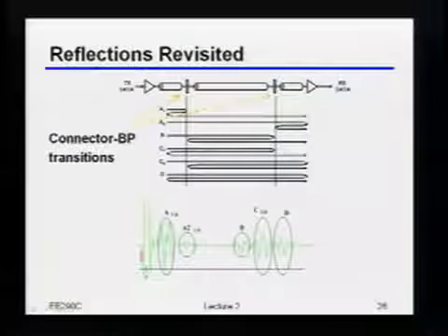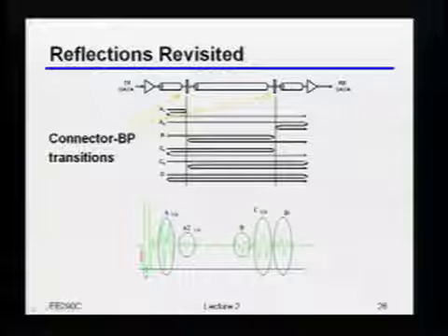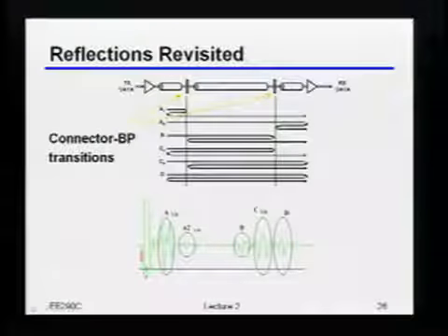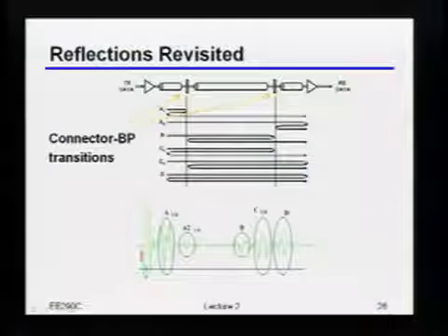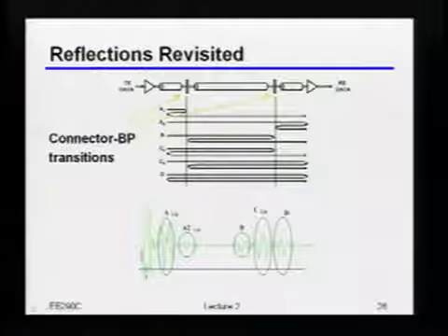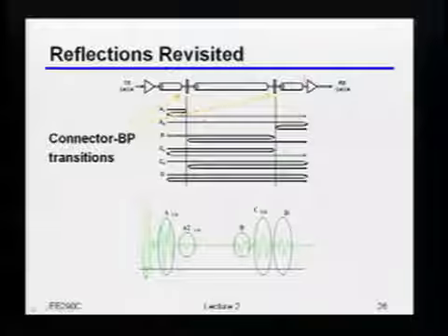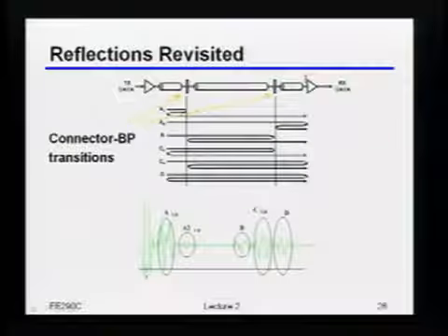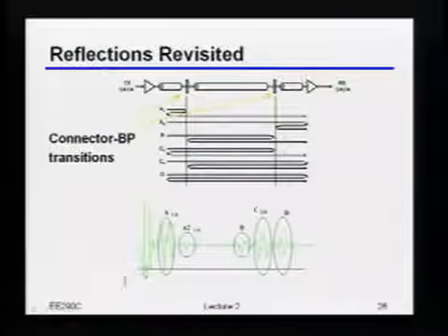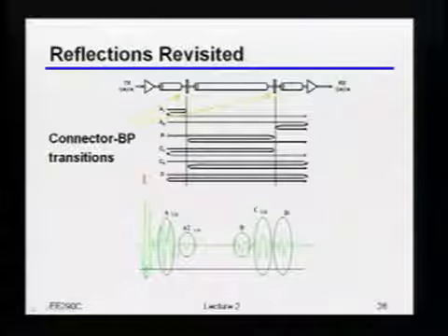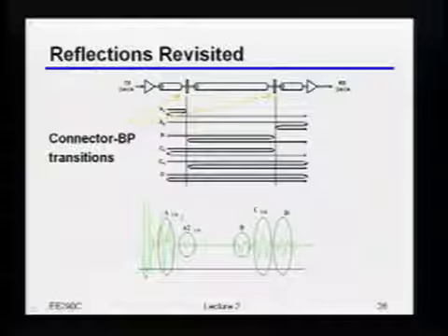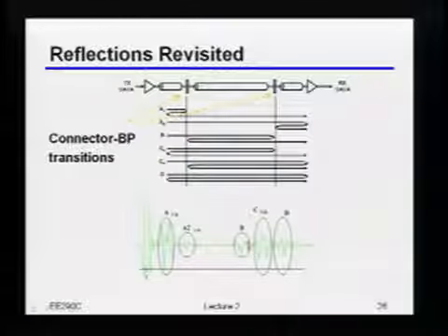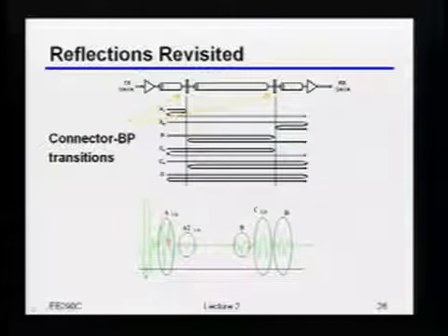Okay, so if I look at this in the time domain, for those of you who are familiar with wireless, this is a lot like so-called multipath effects, right? Because I have physically different lengths of time, or different lengths of actual stuff that I've traveled, to finally make it back onto that receive point. So if you looked at an example where I put in 1 bit at a particular time, and then looked at all these little things that are happening afterwards, these groups of reflections, you could figure out roughly where they happen, just based on how long it took them to show up at your receiver.